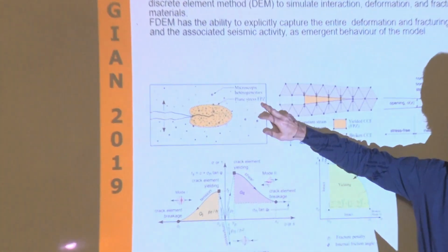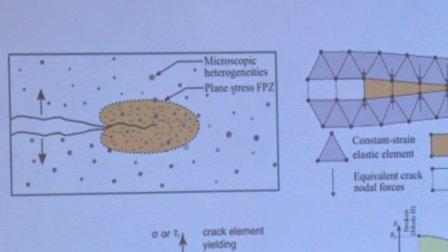Some look at what is the stress of it. But start thinking that maybe it's not really the stress that is creating the failure, but actually it's the fact that I'm pulling apart, so I'm creating a concentrated displacement. I displace two sides of my body, I stretch them to a point that my body cannot accommodate that local displacement anymore and fails. And this happens in an area that is defined generally as fracture process zone, FPZ, fracture process zone.